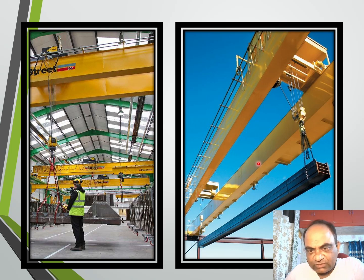So that's it. Here also, yet another crane is there with the double trolley. You can see one crane is there, two girders are there, but two trolleys are moving. Again, there should be an anti-collision device between these two trolleys. Otherwise, these two trolleys may collide with each other in some cases if the operator is not vigilant.